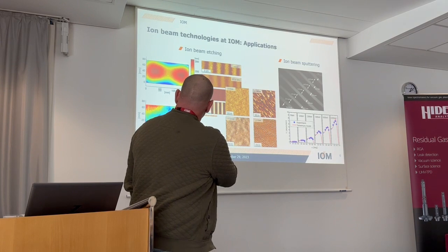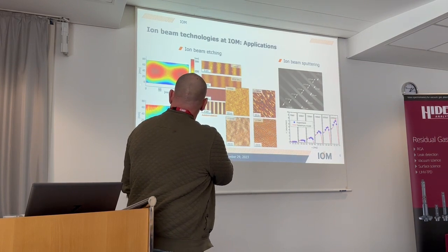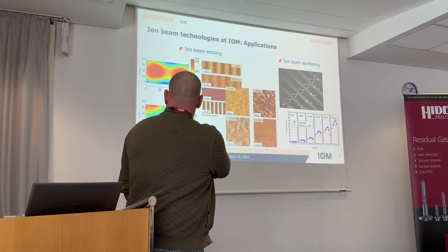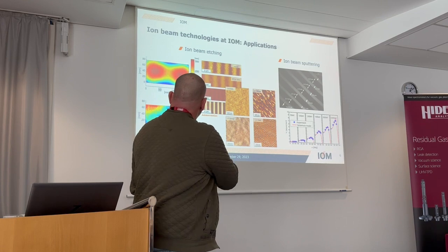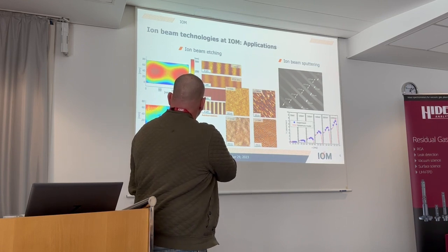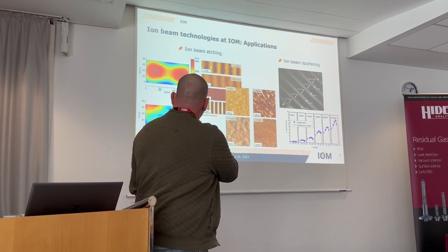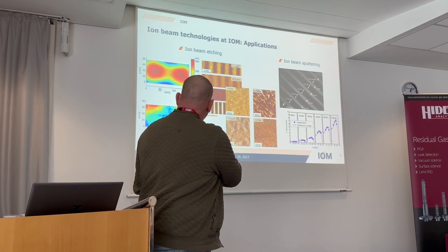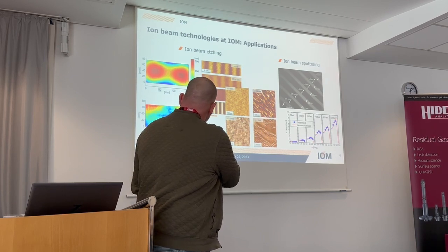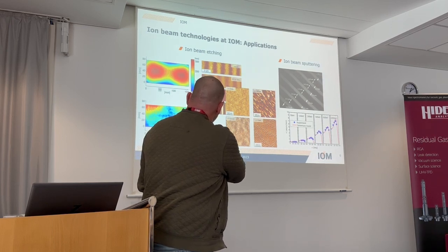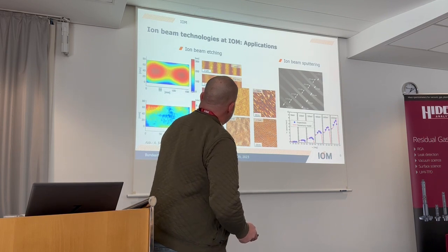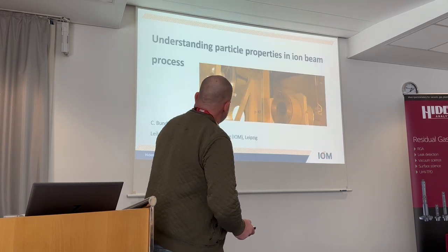Here the size is less than 0.5 nanometer in height, but it's still a grating. You see it here, the autocorrelation is much better. Or here's a surface, a large scale mirror, Serrador, 80 by 150 millimeters, and this is the offset from the target shape of the surface. By ion beam etching, you can reduce the offset from the target shape by a factor of 50.